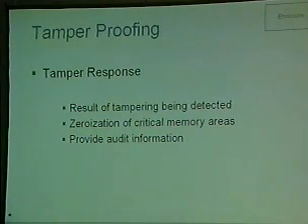Many times tamper response circuitry requires a battery, so the system can have an active tamper envelope even while the system's powered down, and that is very difficult for engineers to design, especially when you're using ion and radiation detectors. Those tend to be relatively costly, and they can be very difficult to implement. Sometimes you might detect tamper, but it may not warrant a zeroization. You may want to audit the information. It's another resultant of detection.